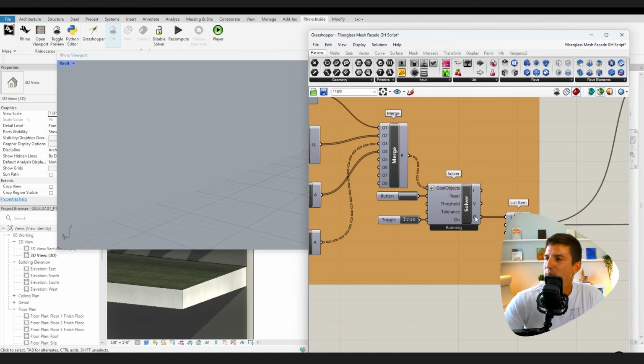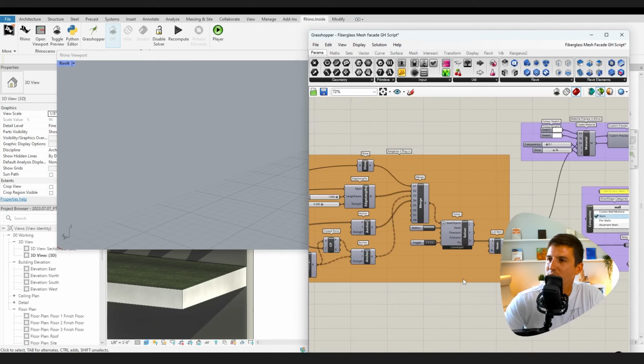It's going to output more than just the mesh geometry, most likely, so you can filter that with list items. If I hover on this, you see that there are actually 15,000 locally defined values that come out of this. A lot of them are null components, meaning zeros. That's not an error, but the only thing we really need on that is the main mesh. And once again, you have to show that mesh into the merge, into the goal objects as show.